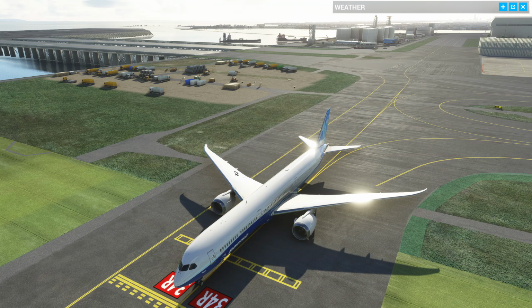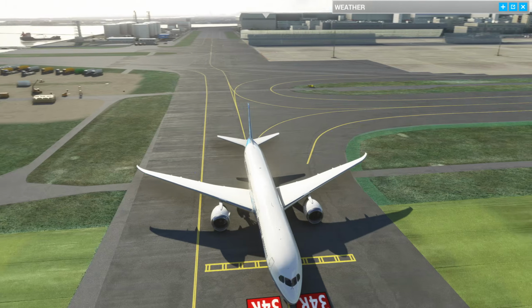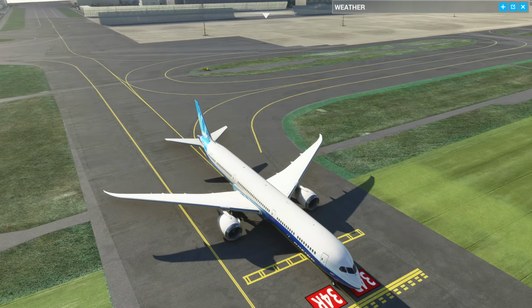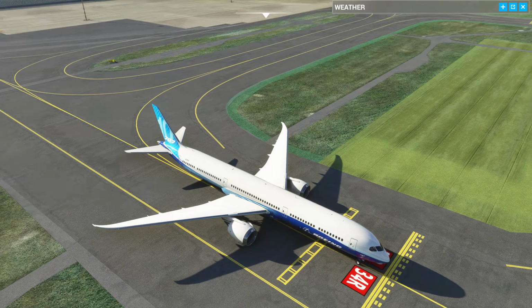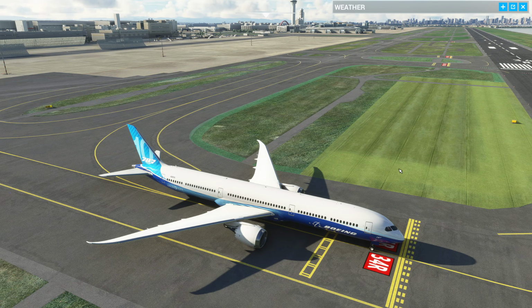That only applies to the fixed derate, not the temperature derate, although in practice it doesn't really matter. That's a technicality. So the message is, if you're using a heavily derated takeoff in a 787 and you have an engine failure, you have to be very careful when and if you want to apply extra power. Adding full power whilst on the runway is not necessarily going to be the best thing for you to do.